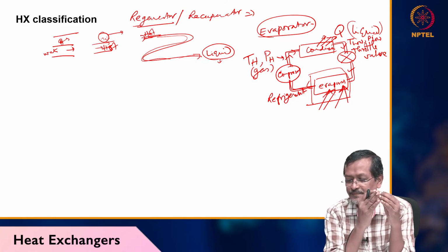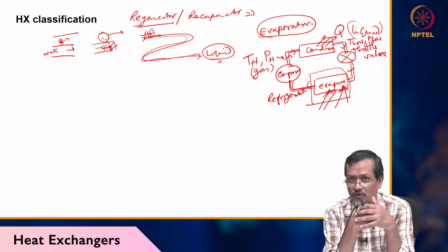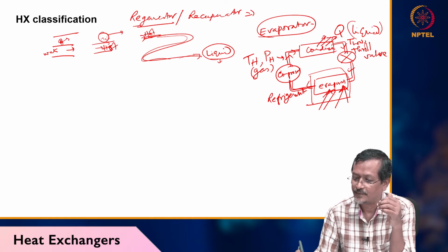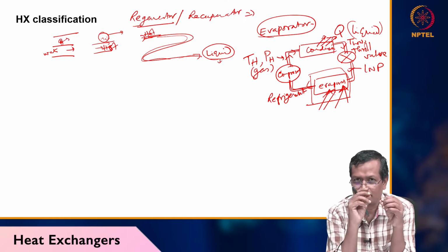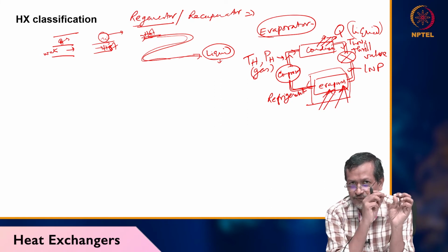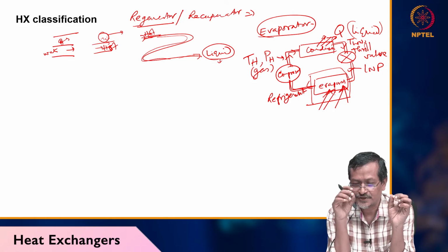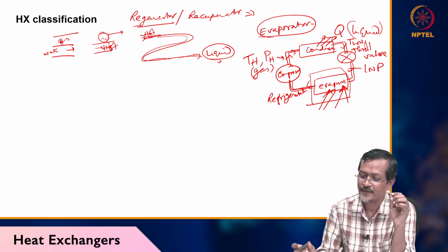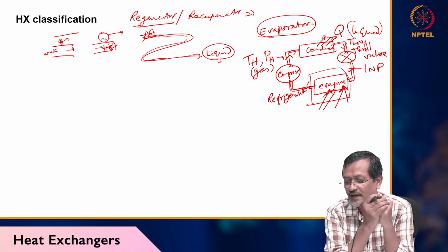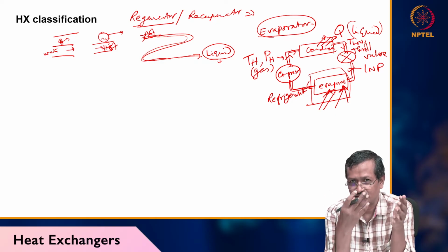So that low temperature pressure fluid will be passing through your throttle valve. Low temperature, not pressure. Pressure will be low. After the throttle valve is a very narrow restriction you create, and slowly you pass fluid through the restriction. So pressure will be lower after the throttle valve, and the low pressure fluid will be going to the evaporator chamber. Evaporator means inside the fridge, and you are getting your system cooled.